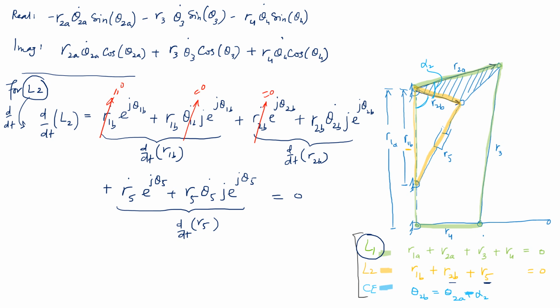And interestingly, R5 dot is going to have a change imparted because of the nature of the joint over here. So this can extend or this can retract because this is the hydraulic actuator of the tractor. So that's why it is going to be the input element. So R5 dot is actually input given to the system. So that's going to be there and having an effect.